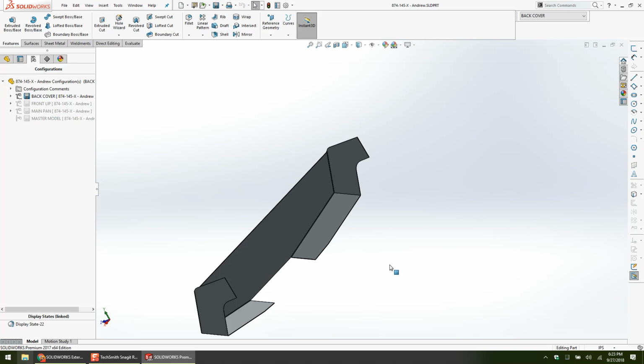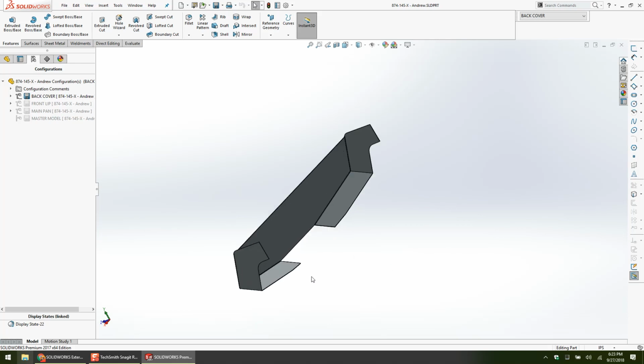Okay, and if you welded 3 feet and you notice that there's like a 3-inch bend here, right in the corner of the box, don't you kind of wish they would have bent the 3 feet and you could have welded the 3 inches? So in the world of sheet metal, if you can remember that, bend the long, weld the short, you'll be a hero.